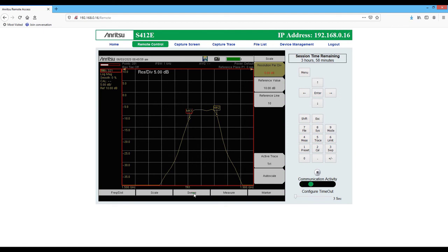When we go to sweep, that is almost the same, except we don't call it RF immunity anymore. We call it dithering, which is what it actually does, dithering on, dithering off. But notice there's one difference here. Configure ports. And this is where we could tell the ports the different plane lengths, if we wanted to get into that far. We could actually change it if we wanted to. We're not going to, but we could.